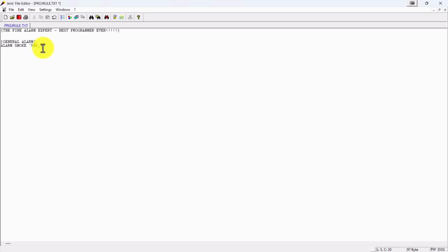So in order for this qualifier to work for all of the smoke detectors, we have to put a wild card. This wild card will represent every last character within this label. So that's why you can have 500 smoke detectors, all be SMK_, but it could be 1 through 500 because each one is unique. And you use this one qualifier to represent all 500 smoke detectors. So now what we want to do is put our divider, which is our semicolon or our colon. I keep getting those confused.